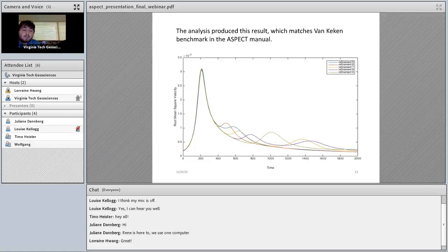You'll see that the first peak, which corresponds to the first major diapir going up the left side of the box, is very well converged for all cases, regardless of refinement. But after this first peak, there is a lot of discrepancy between secondary and, in a few cases, even tertiary features that come a lot more at random. And as I said before, this is more due to the mesh refinement than anything else. This is not the outcome we would expect. We would hope they'd be a lot more converged than this.